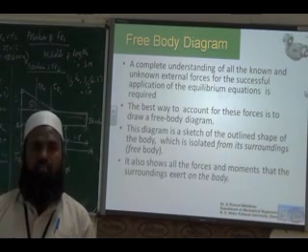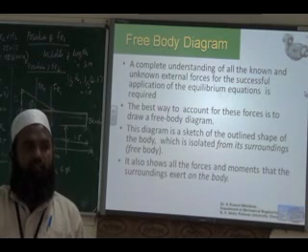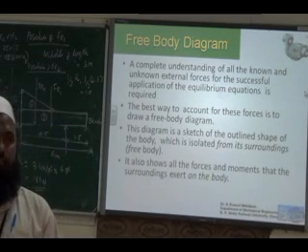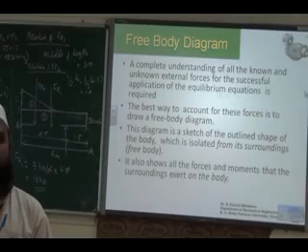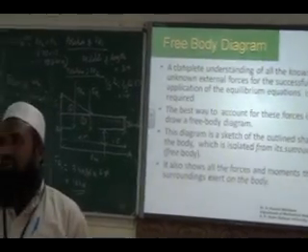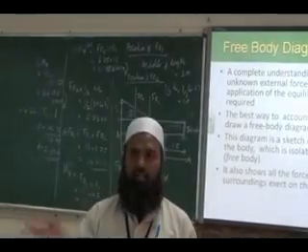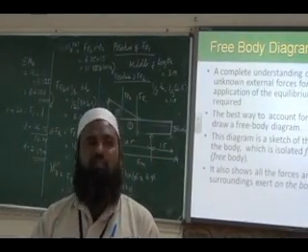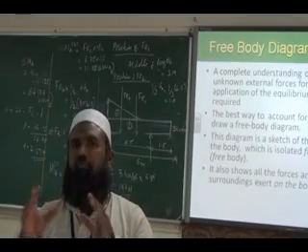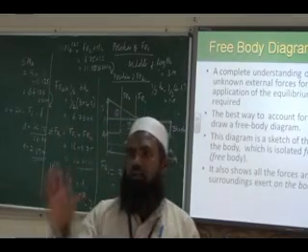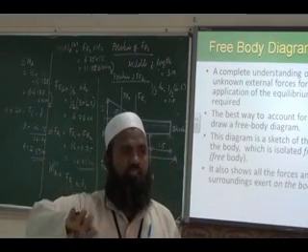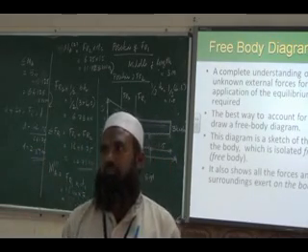If you say all the forces, applied forces are there, then reactions are also there. We apply some force, and according to Newton's third law of motion, an action will produce a reaction. Okay. So if you apply some force, there will be some reaction also. So a free body diagram should represent all the forces, known and unknown forces.